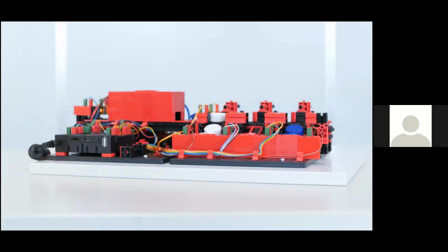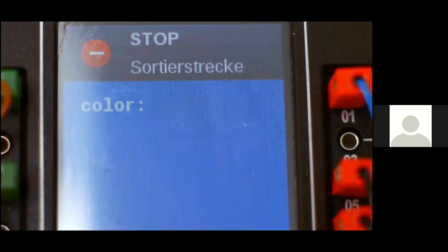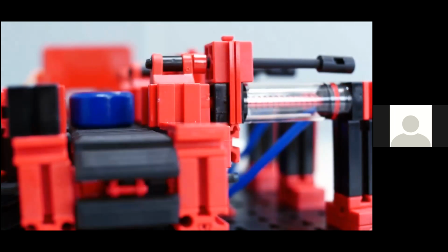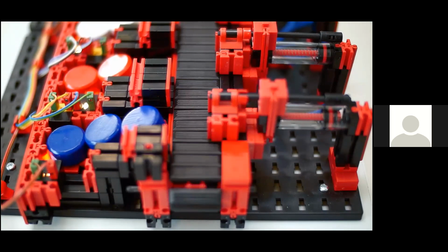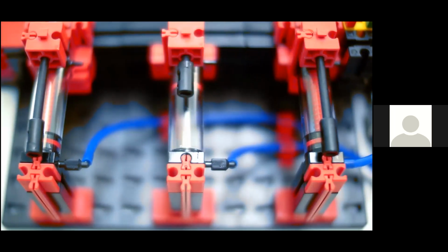Now, as with the models we've looked at before, the standard 24-volt version has a relay board for motor polarity reversal and both a multi-pin connector, again, 34 pins with a grid of 2.54 millimeters, as well as additional PCB terminals with pushing connections for all inputs and outputs. And again, you need to provide the PLC and the programming. There is a 9-volt version available this year. Again, it comes pre-wired to a pre-programmed TXT controller, and 1 120-volt power adapter is required with that.